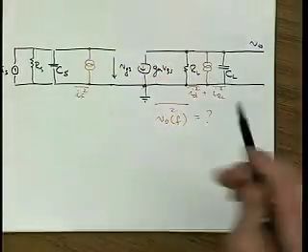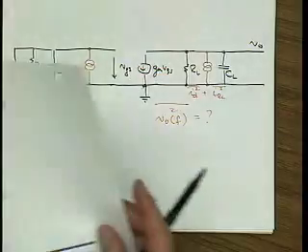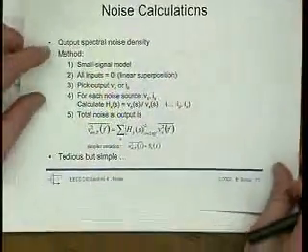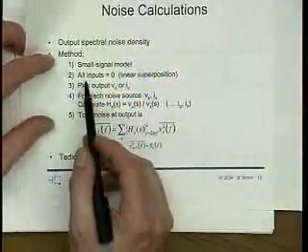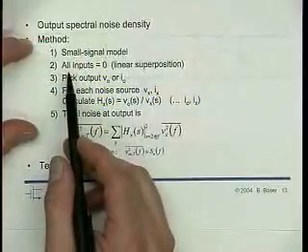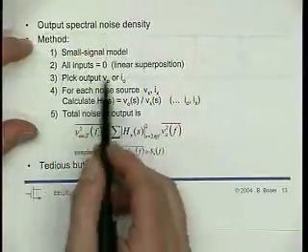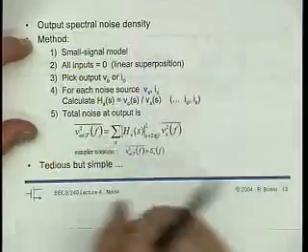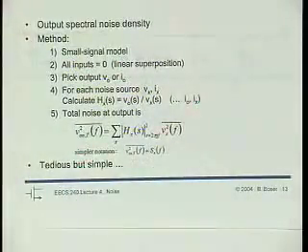Okay, so if we go back to our computer program here, then what this really says is that we should set all inputs to 0 first, and the reason really is convenience. When we are dealing with noise, we have one problem on our hands, so we don't want to deal with all our other problems at the same time.